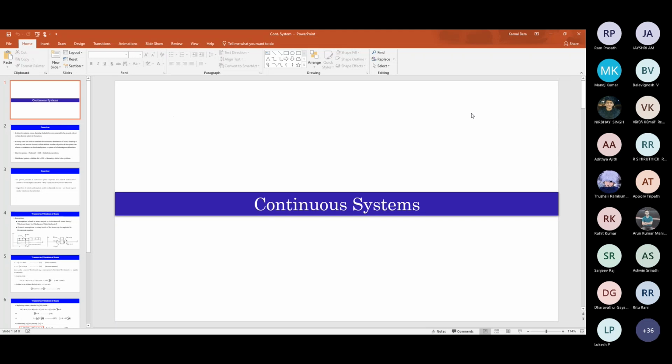We'll see that the closed form solution for the natural frequency is possible, because our aim is first to find the natural frequencies, mode shapes, and then the response, as we have done so far for single degree and multi degree systems. The exact determination of frequency and mode shape is possible only for a beam of uniform cross-sectional area, where EI, the flexural rigidity, is constant throughout the length.